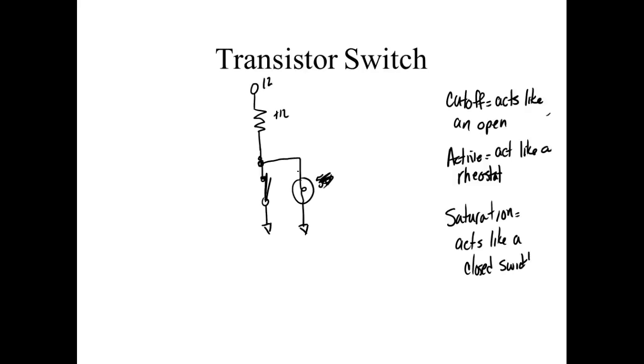There's no difference in potential across a straight piece of wire. Now this resistor is going to drop all the voltage. A while ago, it was dropping 7 volts, but as soon as that switch closed, it's going to drop all 12 volts because this bottom is connected to common. There is no difference in potential across the light bulb. It will not light.